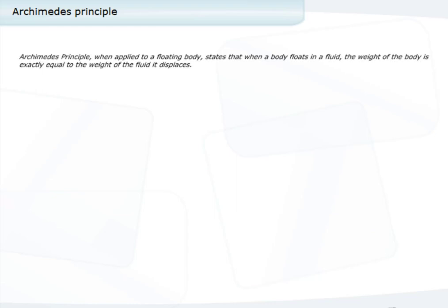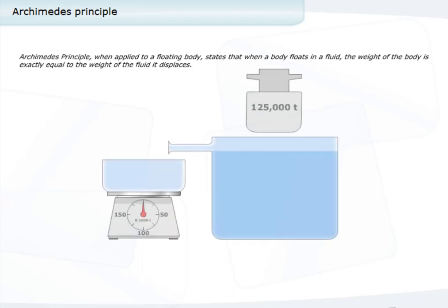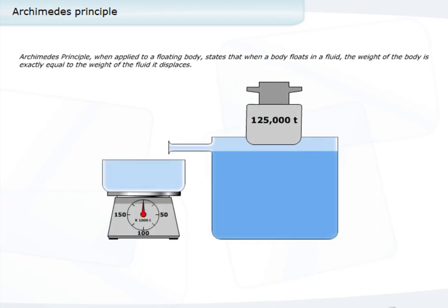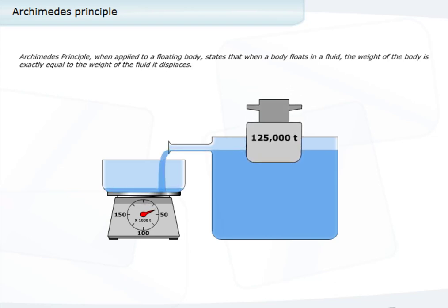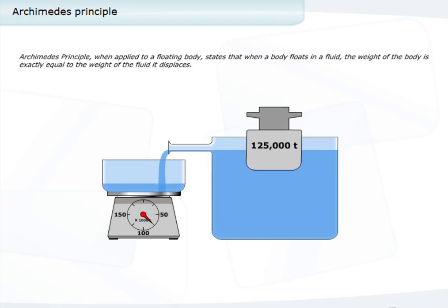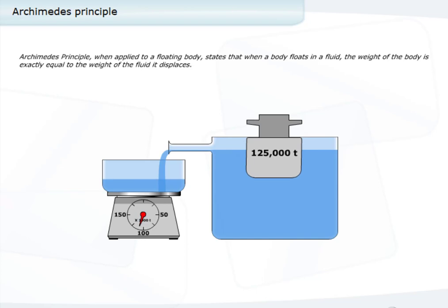In order to understand the principles of stability, a fundamental understanding of Archimedes' principle and how it is applied to a floating body is required. The volume of water displaced by a ship can be calculated by determining the underwater volume of the ship, knowing its draft and underwater shape, and then converting this volume into weight of water displaced by multiplying by the density of the water. Alternatively, the weight of the ship can be calculated knowing the weight of the ship's structure, cargo, bunkers, stores, and anything else on board. These two quantities should be the same and are known as the ship's displacement.